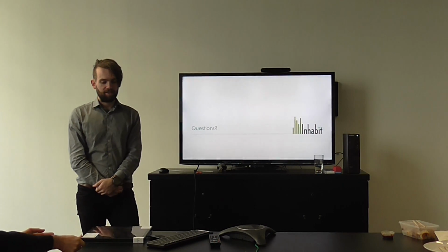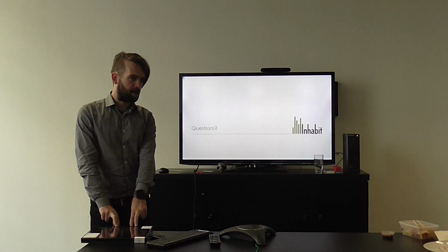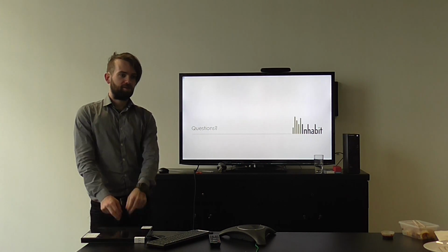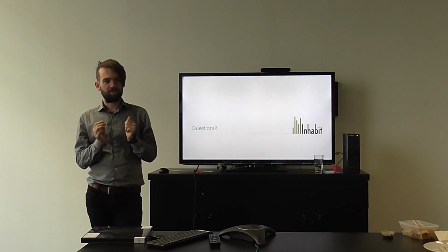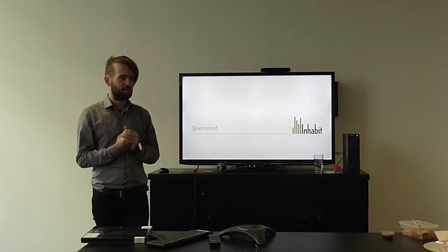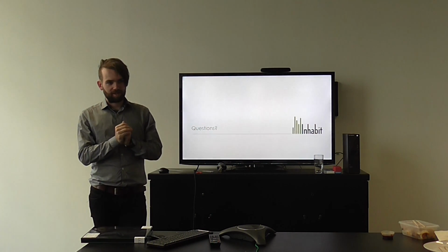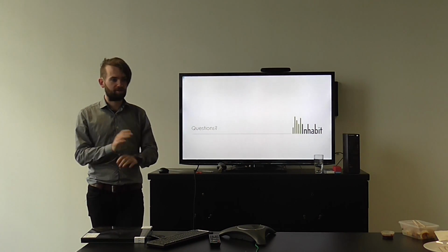Yeah, it's the seal inside the IGUs that is a little bit more critical. There may be a small section of edge which might deteriorate slightly, but typically it doesn't really affect the performance of the panel. There is actually a level of edge bleed on laminate that's usually minimal anyway, so it's not as much of an issue.